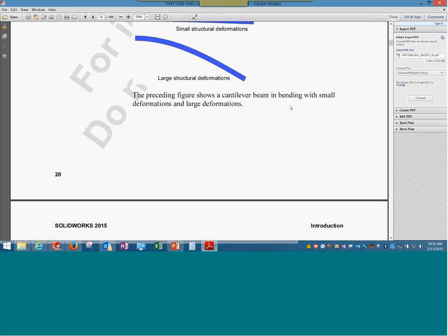We need to have either dynamic or a nonlinear analysis to handle. In a static analysis, the matrix condition or the overall stiffness of the geometry is the same throughout the analysis. So that differentiates things, or that tells why we need what.